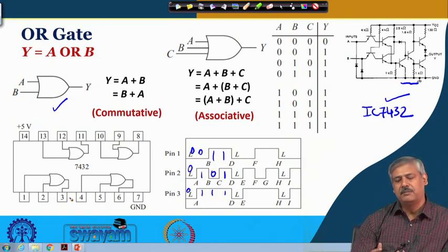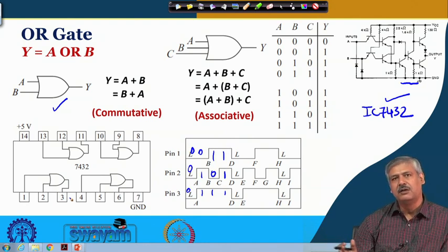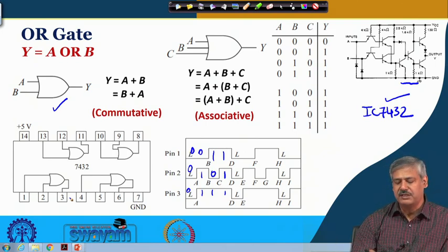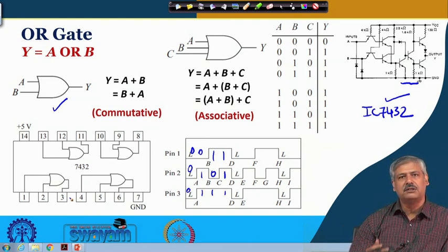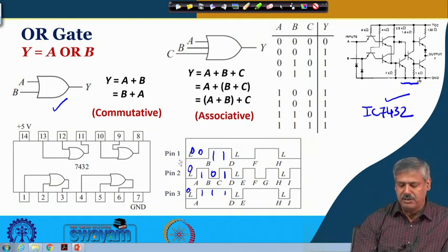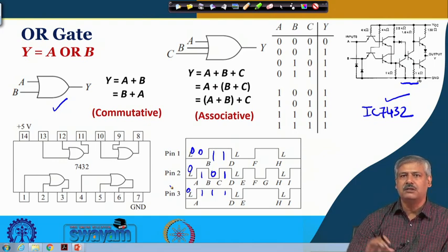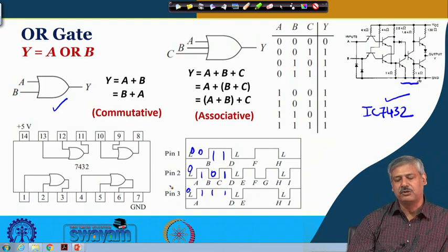Again, I have noted before that if the time scale is expanded, by which you can visualize nanosecond order time indices, then you can see the propagation delay involved in this timing diagram based representation. And of course, there is a truth table based representation where, for A and B at pin 1 and 2, if any of them is 1, the corresponding output in the truth table will be 1, and when both of them are 0, the output will be 0.